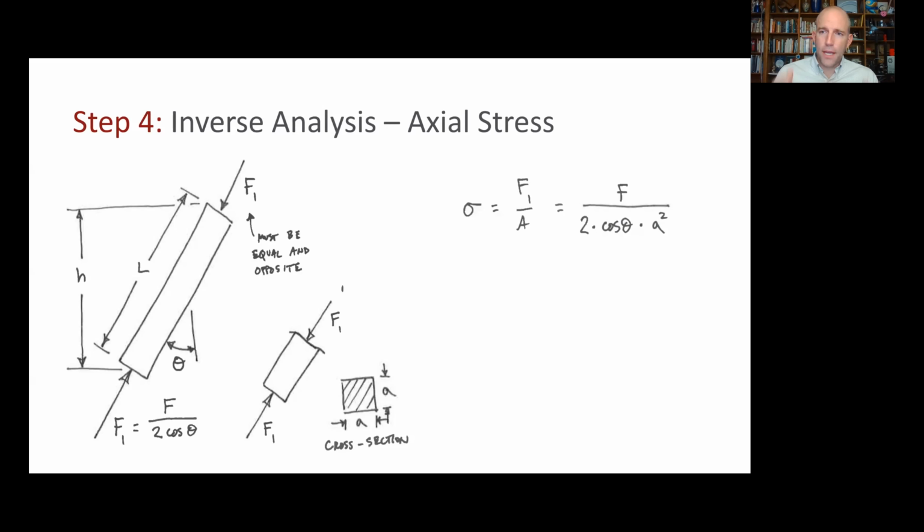And at the end, you should have that parameter equals some function of the force, the factor of safety, maybe other parameters. And one of the tricky things here is to choose which parameter you solve for. In this case, you should choose one for which mass will uniformly increase as that parameter increases. So the simpler the relationship between that parameter and mass, usually the better. Although we can always correct this later, it just makes the algebra messier.